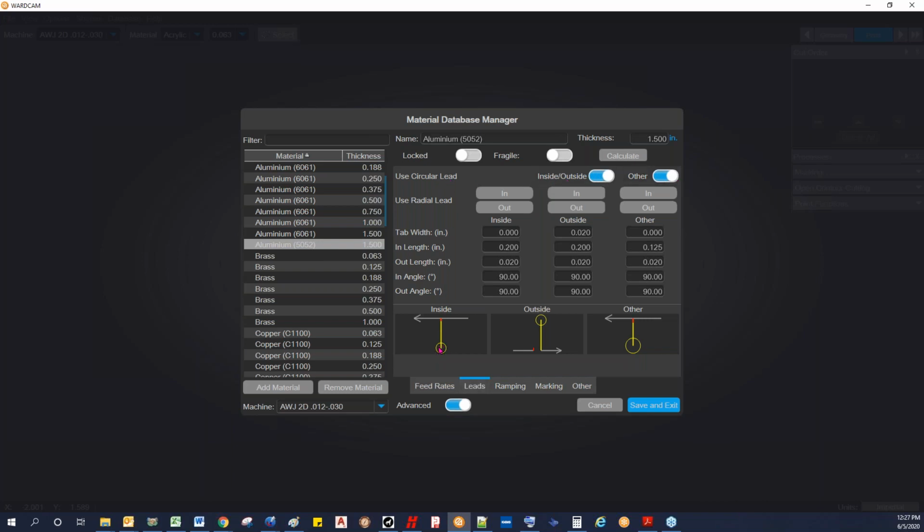There are a couple scenarios where we can use a circular pierce. Either if you're doing low pressure piercing of a material like glass, which might shatter if you pierce at high pressure, we'll typically do a low pressure circular pierce. So the pump will go into low pressure and go over and make a bunch of circular pierces at the various pierce points, and then the pump will go into high pressure and pierce through those holes that you've already made and do its cutting.